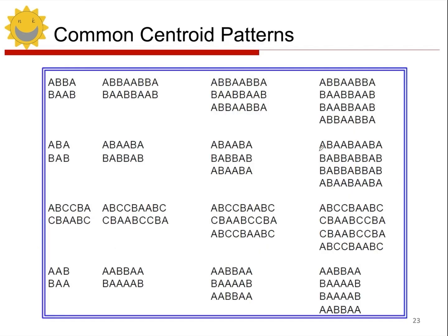All right, this table shows some frequently used decomposition layouts for common centroid matching. Most of the time, it's about matching two components, such as A and B. So how do we place them? The simplest way is ABABAB, which is a relatively small decomposition. If we want to suppress the higher order, we have to decompose it more, right? We even have to decompose it like this. If we decompose it like this, it suppresses higher order gradient changes.